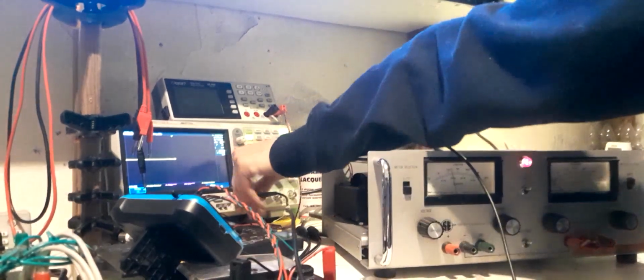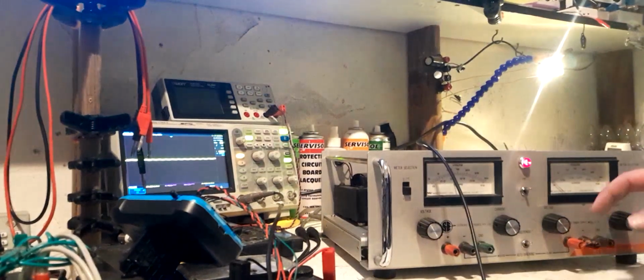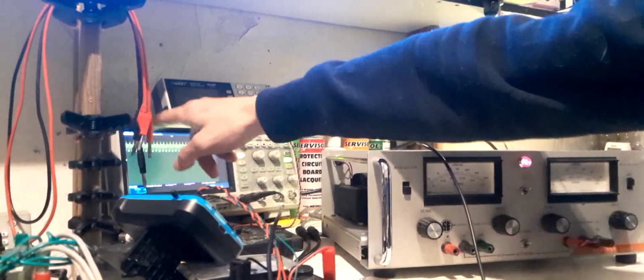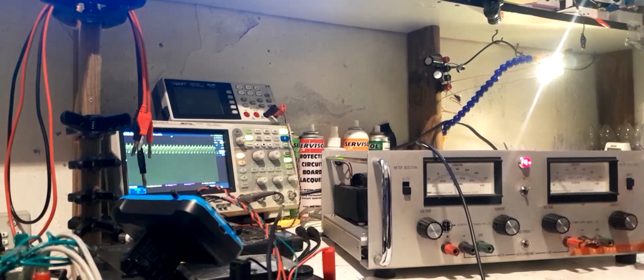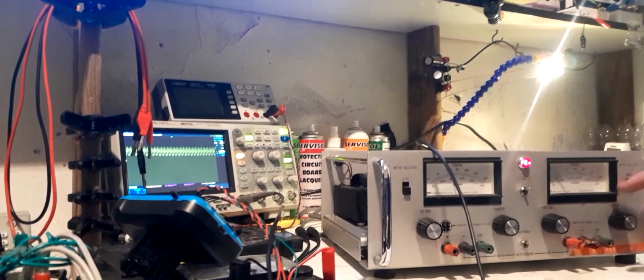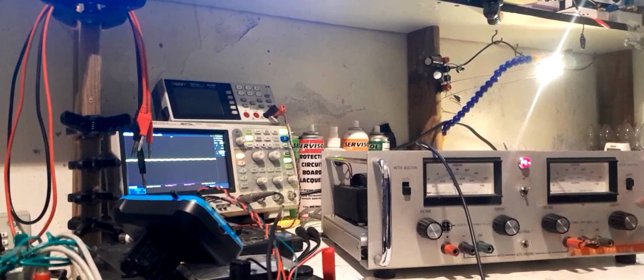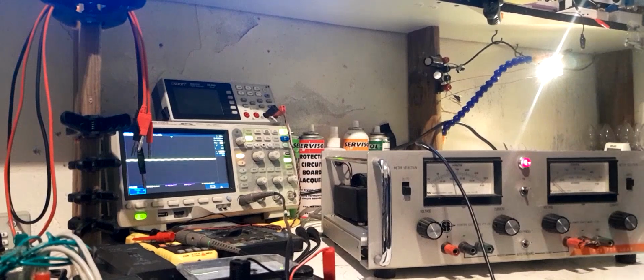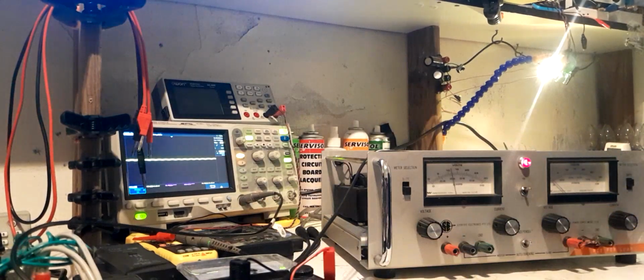It might look a little bit different on the scope because it's creating an earth loop, and we're probably seeing some of that come through too. That's probably what all those little lumps are that you see at the top there, that's interlaced onto the noise. That's the half rectified 100 hertz coming through because of the ground loop. So we can ignore that part of the waveform, we know what that is, and I've already proven that in the last video on the opamps too, so that's good. Alright,